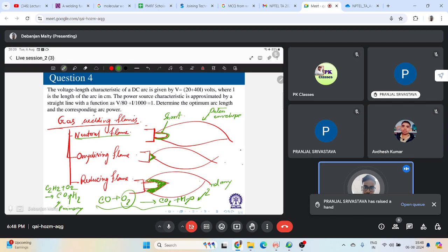So over here, I have used my workpiece as positive electrode, right? And this is also called anode. These are some known things. This is also called cathode, correct? So what needs to be done initially to get the arc initiated? Initially a good contact is made between the electrode and workpiece, and thereafter the electrode is withdrawn. This is a very simple process.